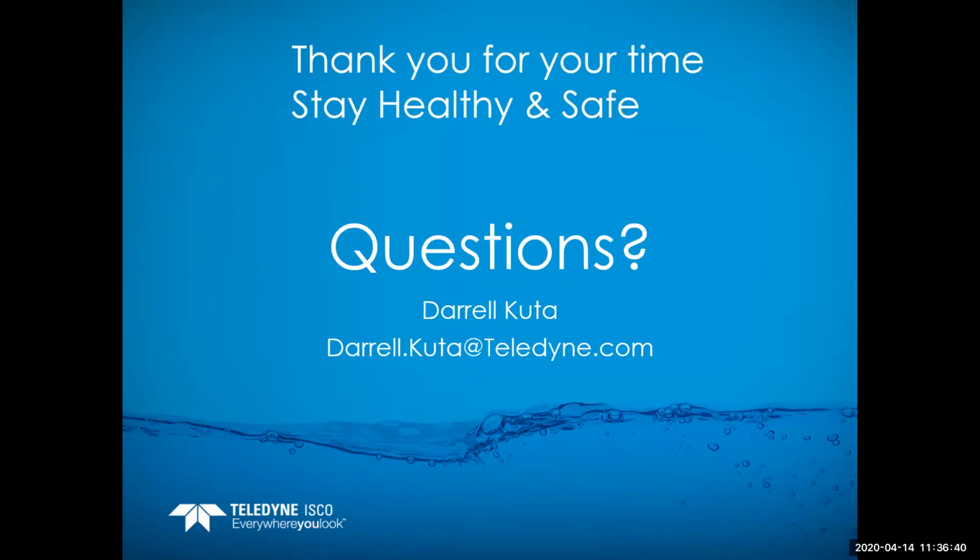All right, that's a great question. As far as the continuous wave Doppler sensors, traditionally they're mounted at the 6 o'clock position in the pipe, but some applications that are known to have debris or silt on the bottom of the channel require the sensor to be rotated off to the side to avoid any of the silt buildup. It's still going to read the level accurately.